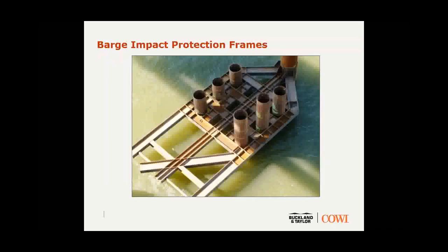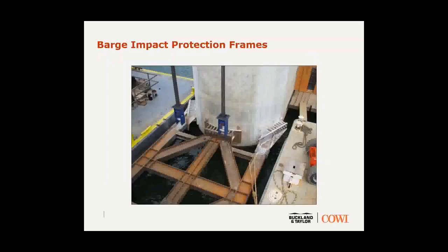That's a picture of one of those frames. In part, you can see it's not connected in the lower left-hand corner. That's because Walsh was also very clever to use it as a pile driving template for those 6 piles before it was connected to the pier, which at this point probably hadn't been finished past that point. At the other end of that, once it is connected to the pier, some fairly massive connections to transfer the loads from that frame into the pier.